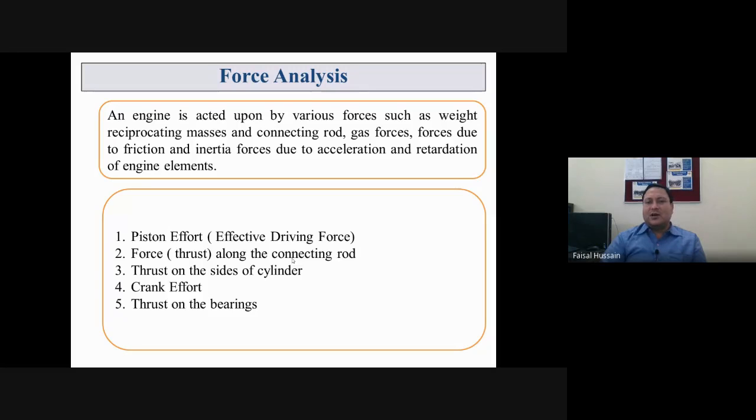If we consider all these forces and put them into these 5 categories: piston effort, force along connecting rod, thrust on cylinder, crank effort, thrust on the bearing, then the system is subjected to, and is known as, the force analysis system.